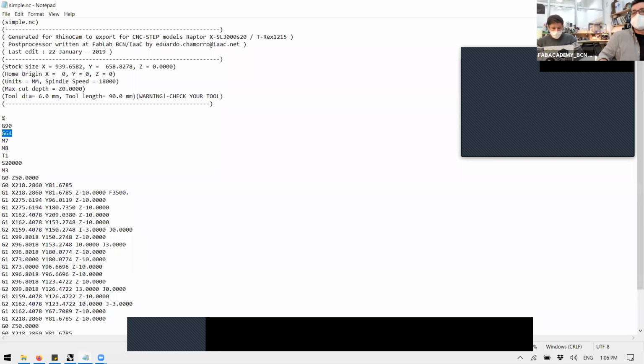So it's important to know this because if your file fails in the first 5 lines, you need to know why it fails. If your file is Gcode, did you export it for the right machine? So the first thing, if I see that my file does something weird, out of scale, is I check: is my file in millimeters? Do I see a G21? No, because this machine actually doesn't accept G21, so we don't need to set it. But in 3D printers, yes. If I don't see a G21 and it's doing things 2.5 times bigger, the first suspect is the Gcode. Yep.